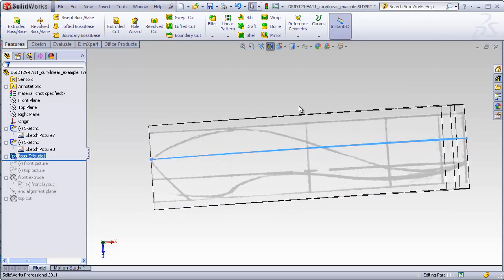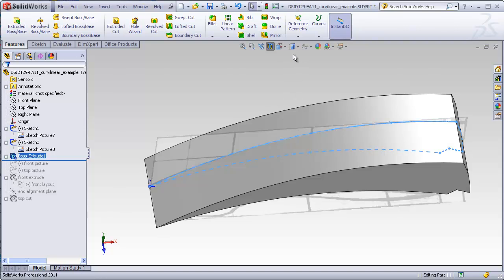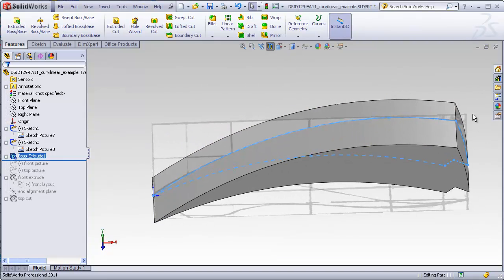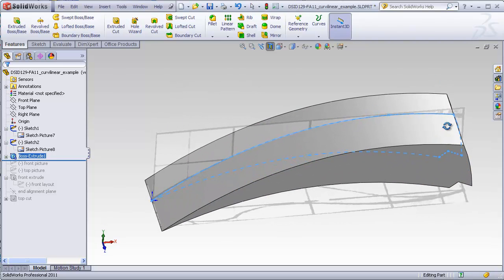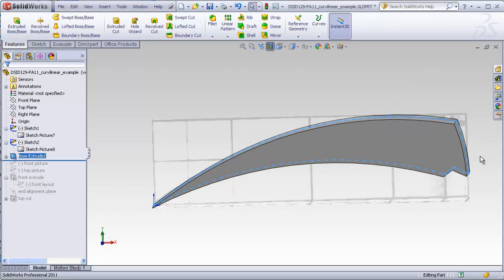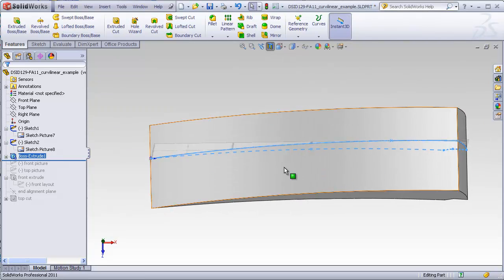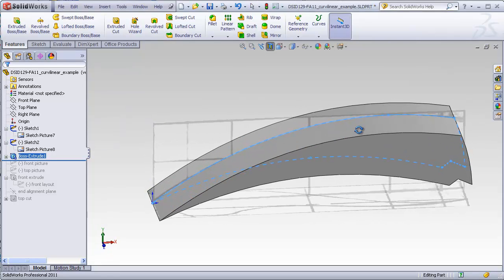through our solid object. Before I do any of this, I want to add a plane at the very end of my object here that's going to represent the maximum 9.24 inch dimension that can be used as a reference when I draw my second sketch. I'm going to parametrically tie it to the first created feature here, so that if for some reason I were to change the length of this in the front view, it would automatically change in the top view at the same time. Adding this plane is not absolutely necessary, but some people might find this conceptually a little easier to understand.